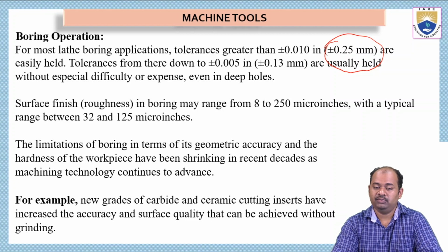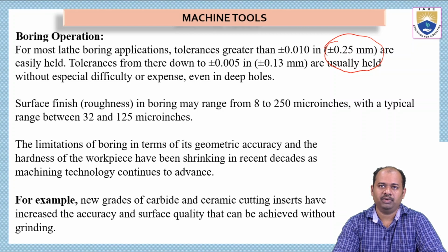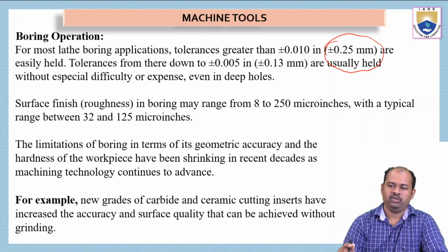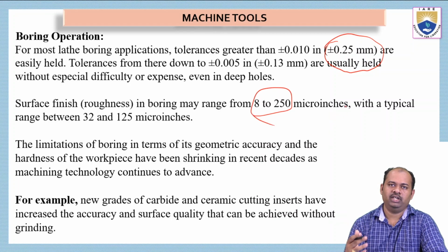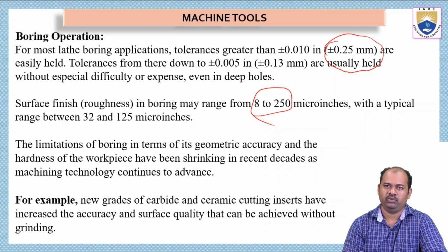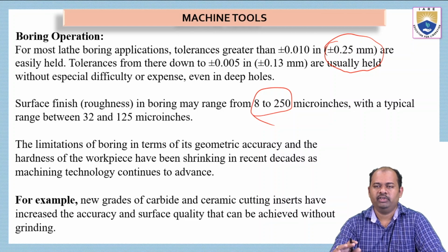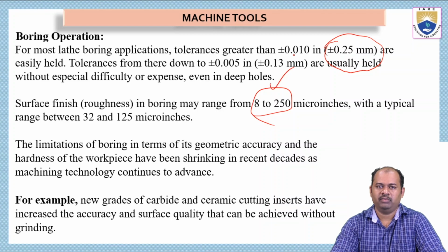And the surface finish which we will get by this boring operation ranges from about 8 to 250 micro inches, and its typical value ranges between 32 to 125 micro inches. Okay, so the surface finish we can get from this operation is 8 to 250 micro inches.